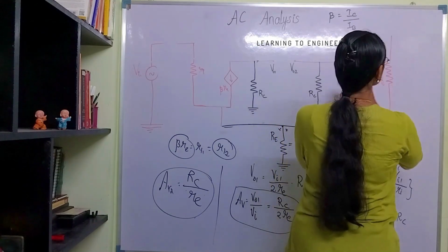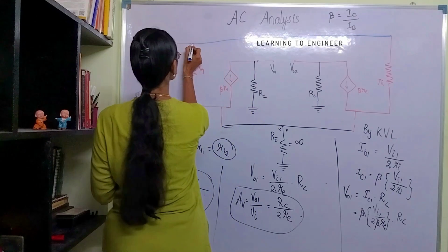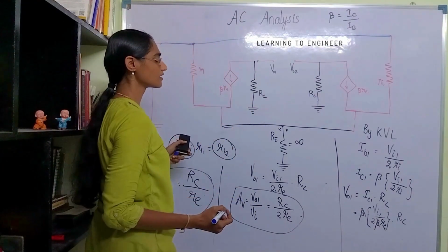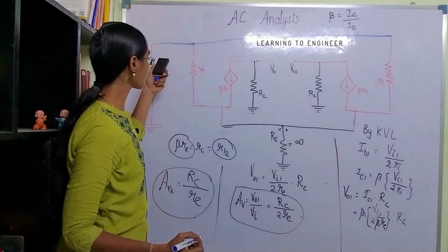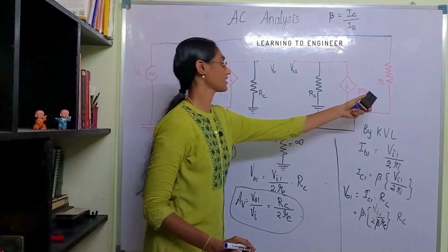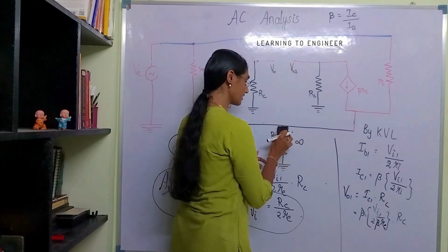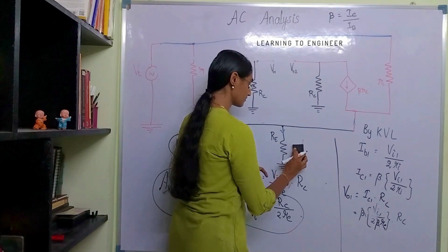The second transistor or the inverting input is also connected to the same VI, okay. So we will have IB because of this transistor, IB1 because of this, and another IB will be here, and both of them will get added and move into the resistor RE, okay.